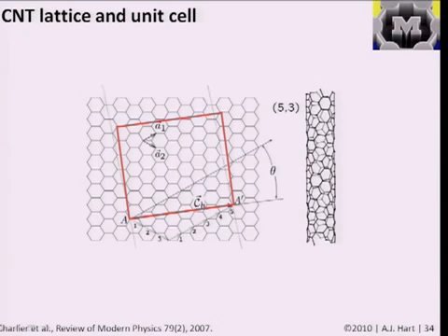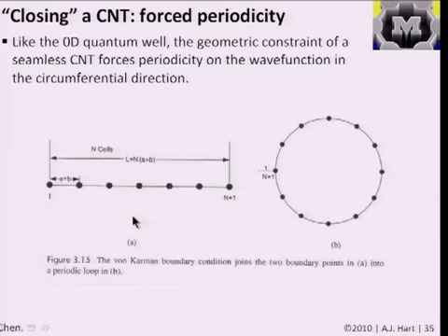So as a recap, remember we saw that nanotubes are this conceptual rolling process of taking a graphene sheet or a single layer of graphite and defining a unit cell and defining a waist-band circumferential vector, and then wrapping the sheet around to form a seamless cylinder like so. And we had to have this geometric continuity where you always connect one lattice point to the other lattice point in order to make a perfect or seamless nanotube.